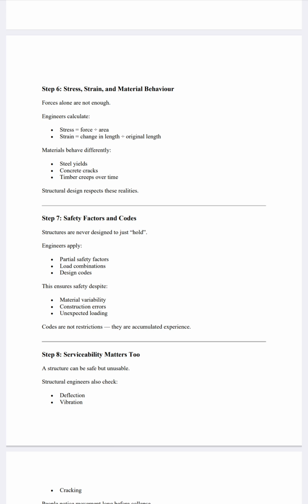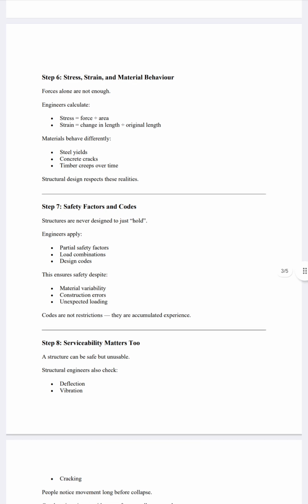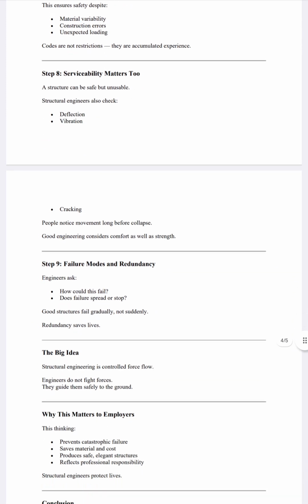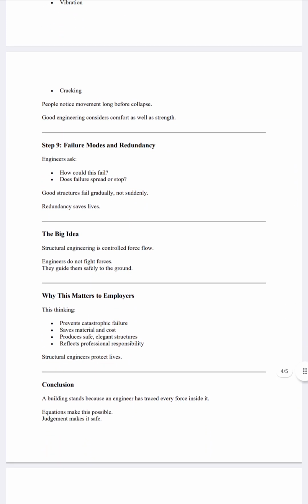And step 8, serviceability matters too. A structure can be safe but unusable. Structural engineers also check for deflection, vibration and cracking. People notice movement long before collapse. Good engineers consider comfort as well as strength.